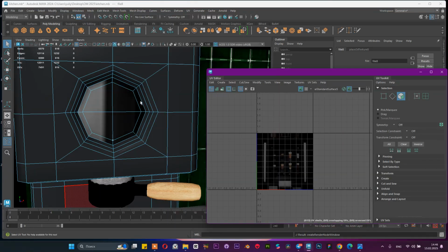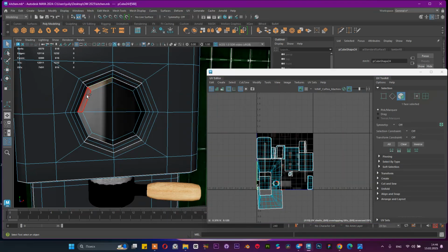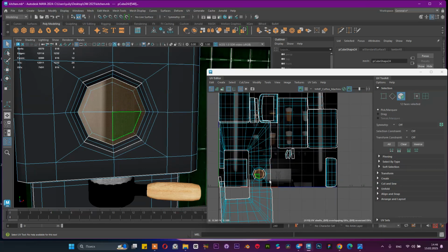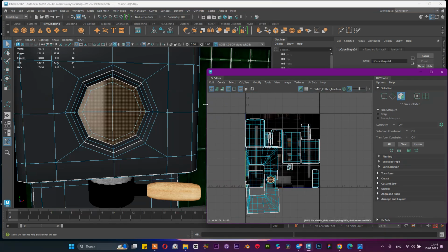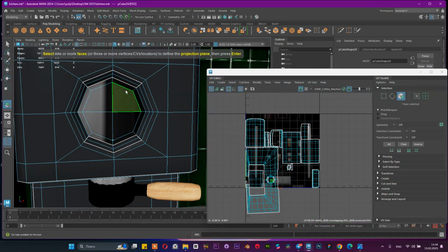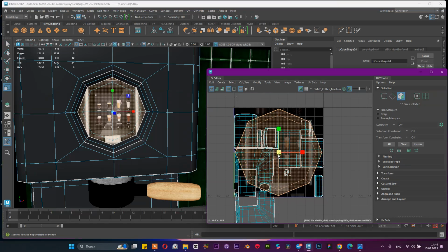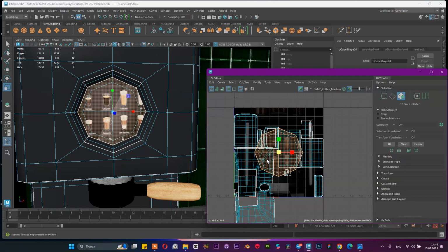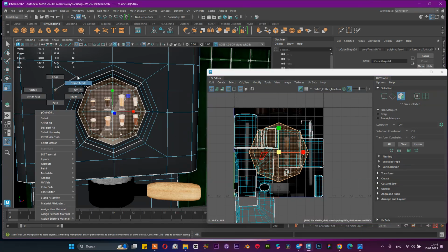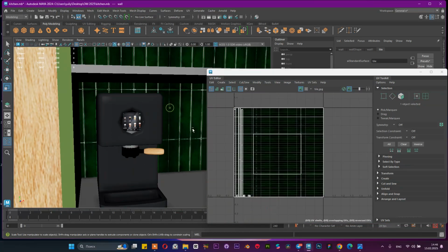And now on the selected faces, we need to change the UVs. We should unwrap this UV according to the entire space. We can create the best plane by pressing enter on the selected faces, and now we can zoom in and zoom out and put this image on this display.